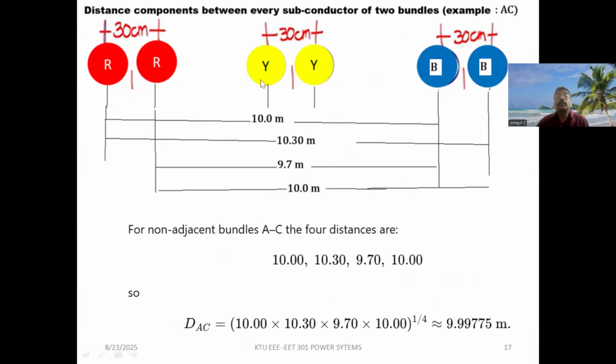Now we will see the equivalent distance between the first bundled conductor and the last bundled conductor, that is R and B. For that, we can write the distances as earlier: the first R and the first B, first R and the second B, the second R and the first B, and the second R and the second B. So the distances are 10, 10.3, 9.7, and 10.7 meters.